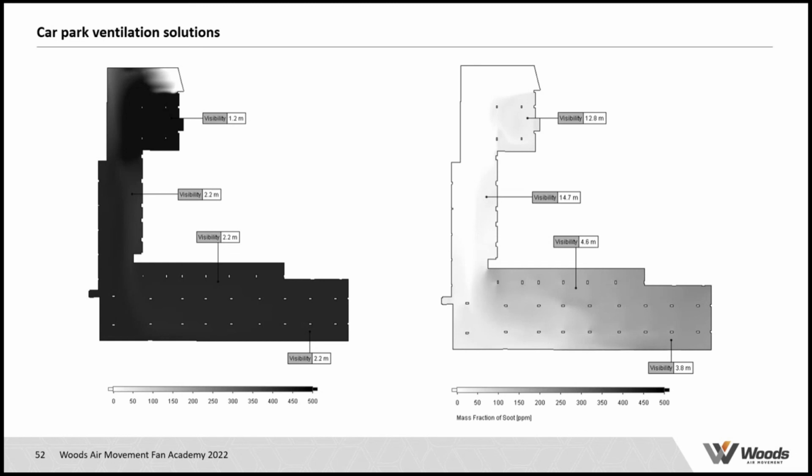Again, if it's a smoke clearance system, which the majority of car parks actually are, because that section 10 is not mandatory in most countries, the image cannot really be used to accept or reject the system. It will give you an indication of what you can expect of the 10 air changes in that specific car park in terms of smoke clearance rate. Whether that shows that smoke is cleared after 5 minutes or after an hour, that's not really relevant. That's not something for which authorities can say it's accepted or rejected. It's purely an indication of what the 10 air changes, probably together with the jet vents, will result in for that specific car park.